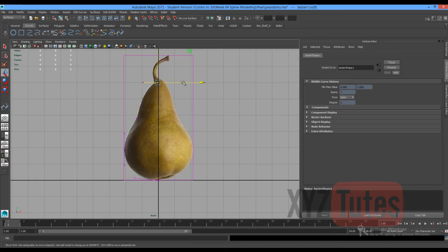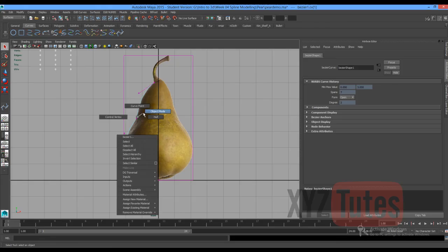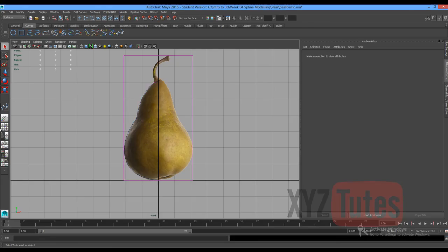And I'm going to leave the top part open slightly. So just adjust this one down a bit. Okay, the important thing is to make sure that this point here is on the origin, so definitely snap that one with snap to grid so it's definitely on the origin. Okay, so I finished adjusting. I'll press Q, go back into object mode. Okay, so that is excellent. So now that's our first bezier curve.